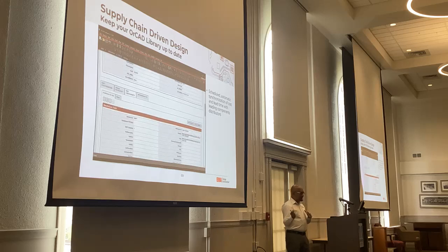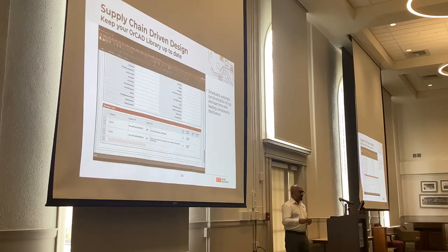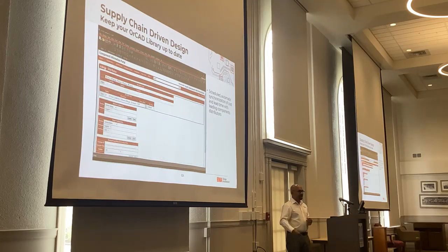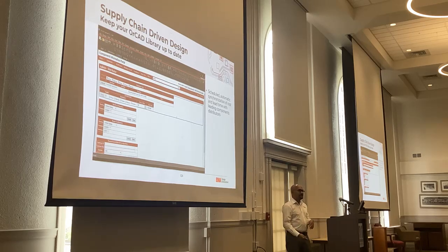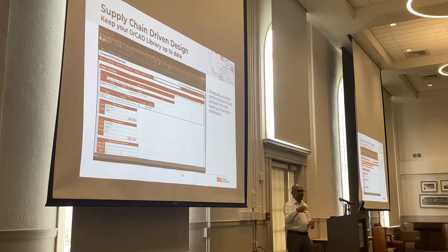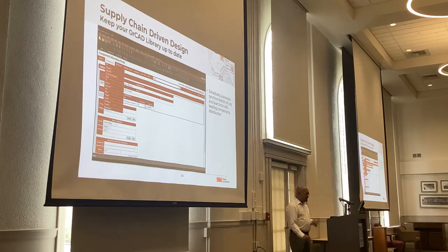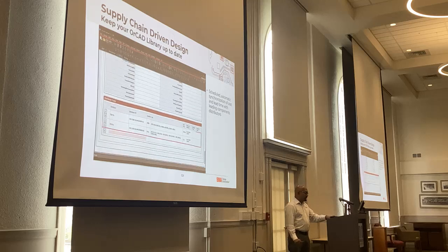The best part is, let's say you downloaded a part from DigiKey or Arrow or Mouser, the information is synchronized. You can set up a scheduler that says, every day I want to synchronize information. I downloaded a part today, I want to make sure that part data is updated. So if DigiKey changed pricing or inventory, or if Arrow changed, based on where you downloaded the part from, it will automatically update that information into your library. As long as you download it from their website, that link is established when you download it.